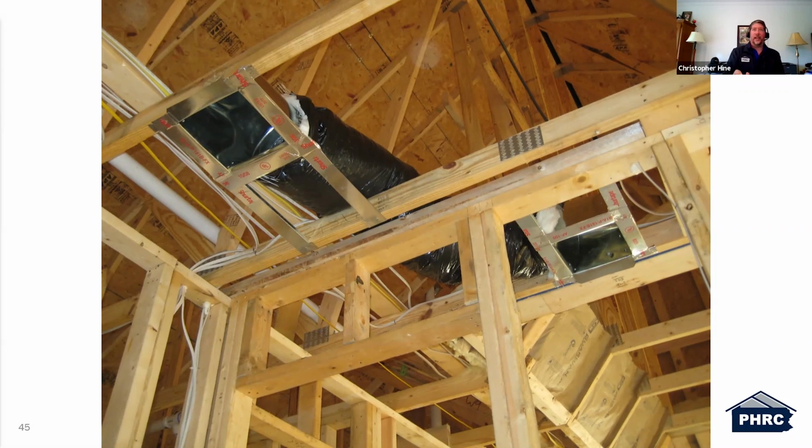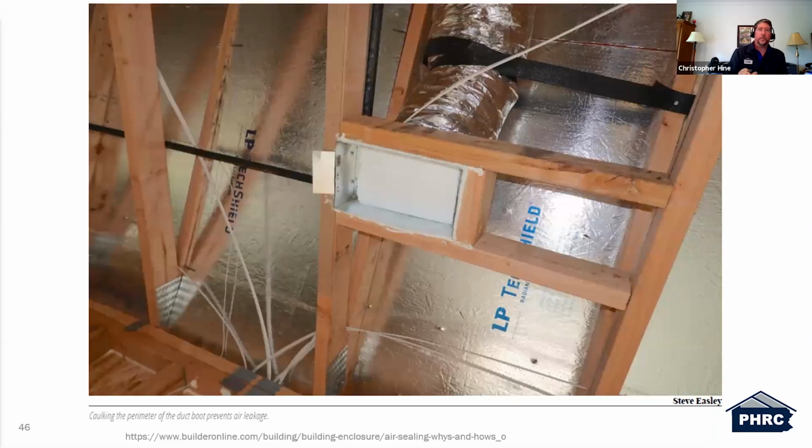And with that being said, that means that this over here is going to be under pressure. So if it isn't sealed, it's going to leak between the drywall and that opening into the attic. And that's what we don't want. We don't want to be pushing, whether it's through pressurization of the system running or stack effect, that conditioned air leaking into unconditioned spaces.